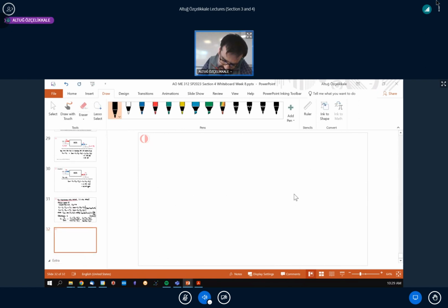Then the heat transfer rate you can obtain as effectiveness times the maximum heat transfer rate possible, and that's going to be effectiveness times C min times the difference of the inlet temperatures. Isn't that beautiful? Look at this equation. Let me call this equation 1. Unlike the log mean temperature difference, it doesn't really involve the outlet temperatures. If you know the effectiveness, based on the knowledge of inlet temperatures, you can calculate the heat flow rate.